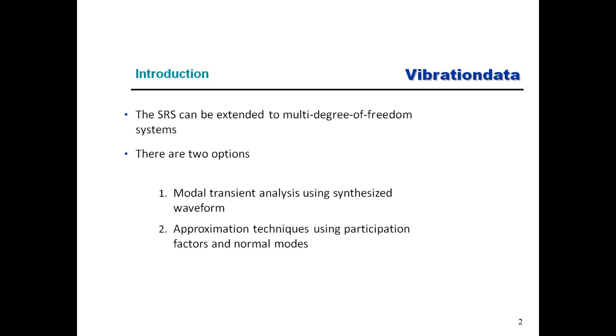Well, this modal transient analysis can take a long time. We can somewhat shorten the time and the memory space by limiting the response outputs at a handful of carefully selected degrees of freedom, and I've done that before too. But as much as possible, that's my choice as method 1.